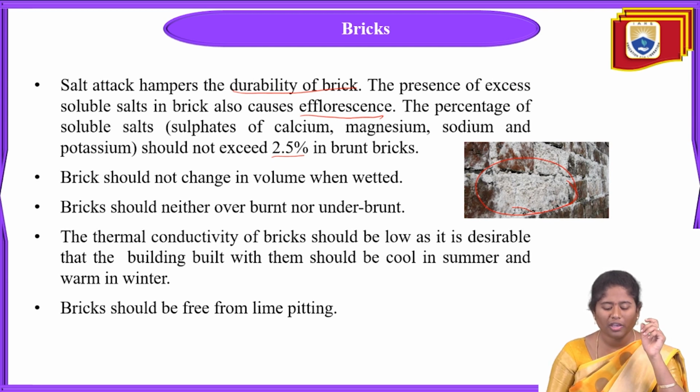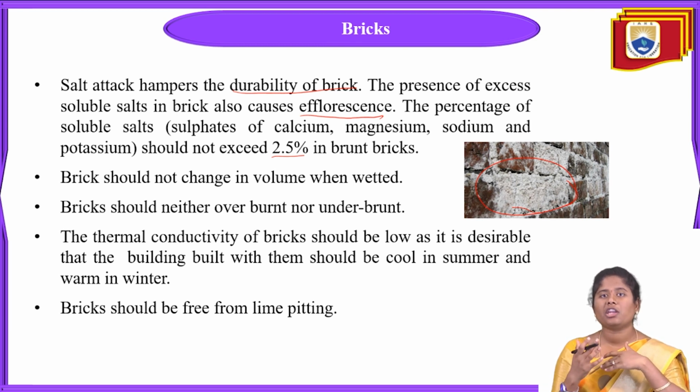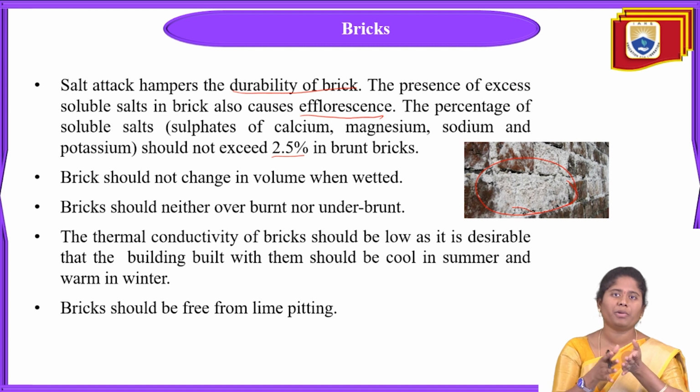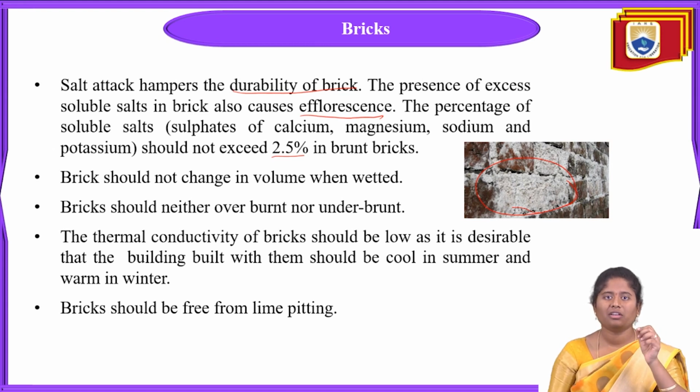Next, it should be neither overburnt nor underburnt. When we manufacture bricks, we burn them, and only then will they get strength. That's why we burn these bricks at a certain temperature, like 1100 degrees Celsius. In this process, the brick should be neither overburnt nor underburnt.